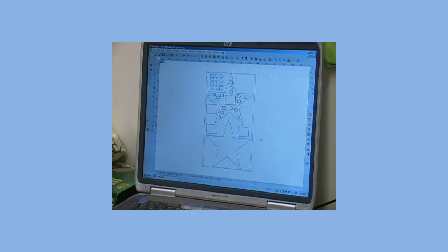If you exit out before you save it as an Enroute file, you will not be able to recover it. You will have a .ncc file for the CNC machine, but you will have nothing that you can edit inside Enroute. So make sure you do save it both as output it to NCC, and then save it as an Enroute file. And that's it for the Enroute portion. Now we'll go to the CNC machine and get it set up.